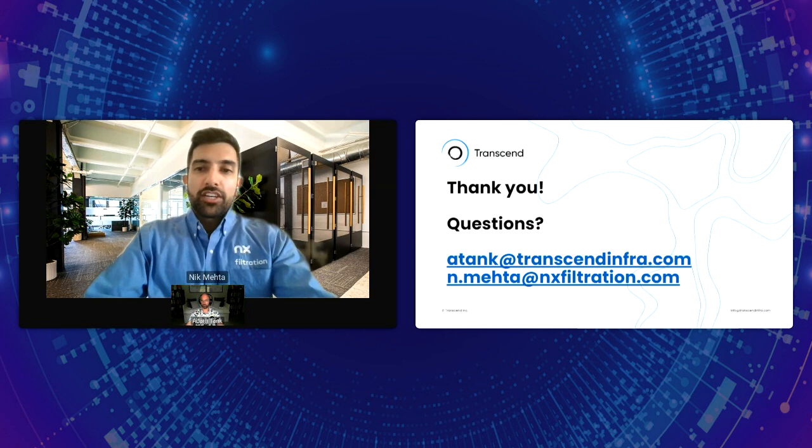Is NX Filtration energy efficient and can be used for domestic water treatment? It can absolutely be used for domestic water treatment. That's another sweet spot application for our membrane. Two of our biggest sweet spots are municipal drinking water, where you're taking surface water, minimal pretreatment, if any, going straight into the hollow fiber nanofiltration membrane, and then producing a permeate that is in many cases ready for chlorination and distribution. In some cases, you may just have a GAC or something simple like that on the back end.